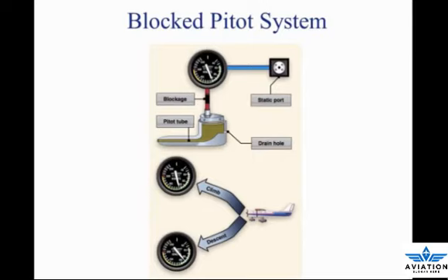The pitot tube may become blocked during flight due to visible moisture. Some aircraft may be equipped with pitot heat for flight in visible moisture. Consult the AFM POH for specific procedures regarding the use of pitot heat.